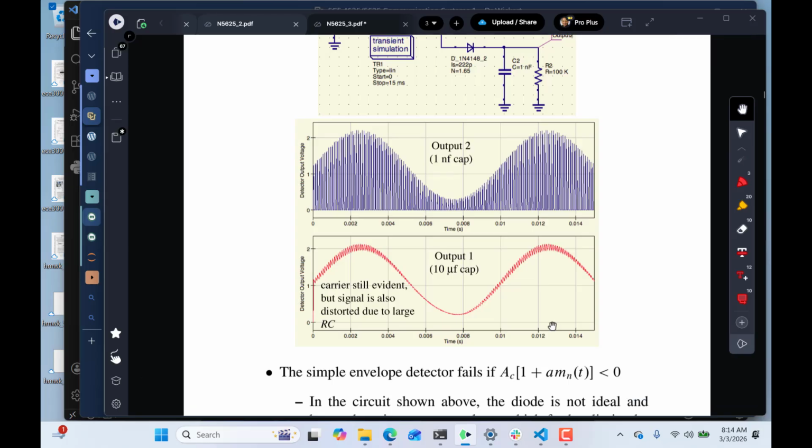So we'll be talking about frequency translation and mixing maybe towards the end of today before I do the review. But in frequency translation and mixing, you always move to a common intermediate frequency, and that intermediate frequency might be 455 kilohertz, which really isn't very high, in the olden days of AM radio. 10.7 megahertz is used in FM radios of old, still to this day. And then in satellite communications, they use 70 megahertz, so that's much higher if you were doing something with an envelope detector, which is still used today, definitely.